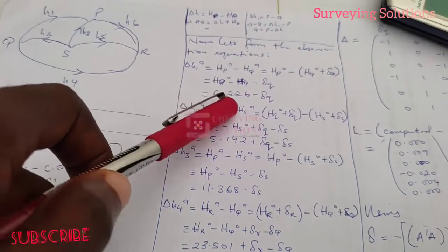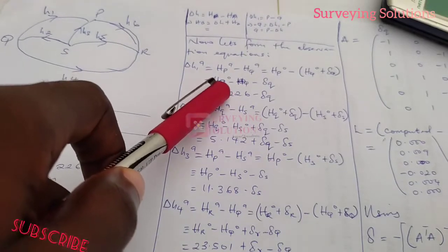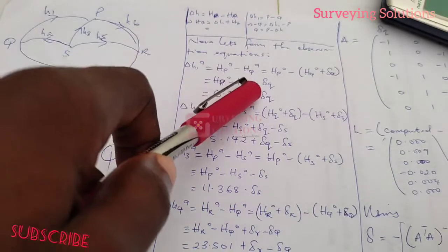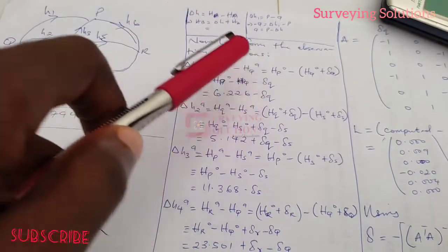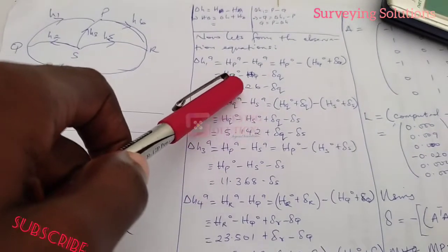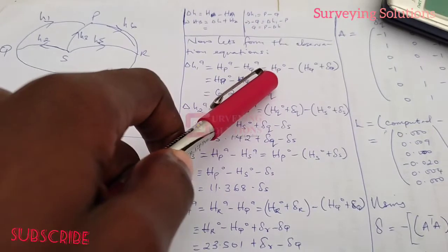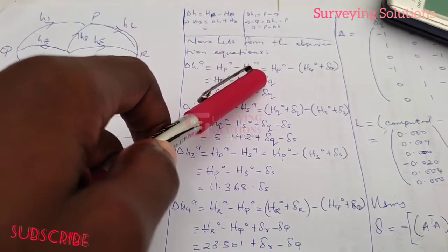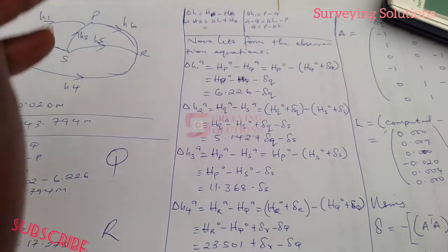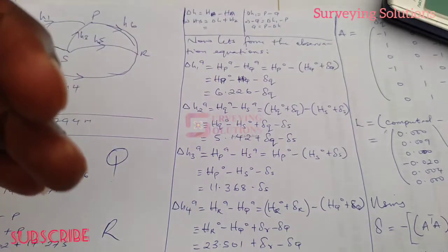So when you subtract these two values, the height of P, which is 150.020, minus the height of Q observed, remember we are dealing with the observed values now, which is 143.794, you would have 6.226 minus the error in Q. Are we together? These things are very, very simple. You can take your time, pause the video, and we believe you will get everything once and for all.